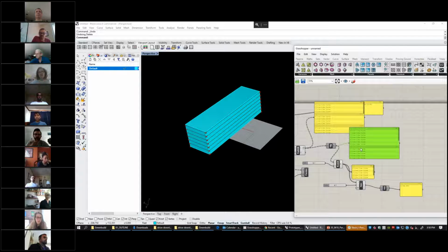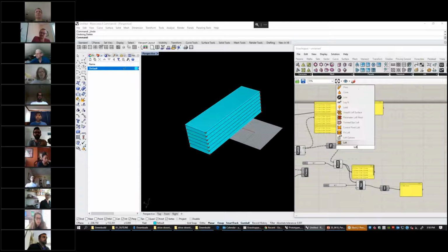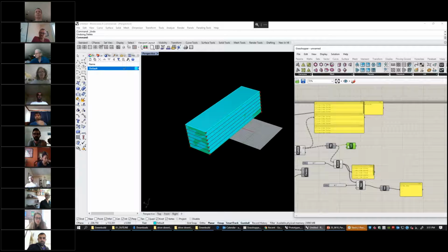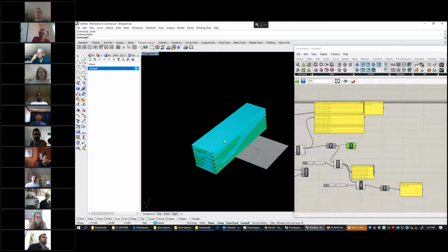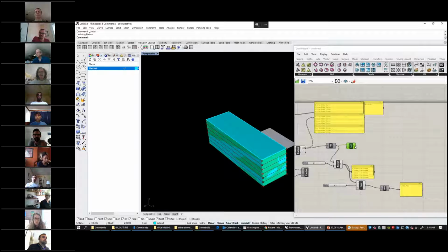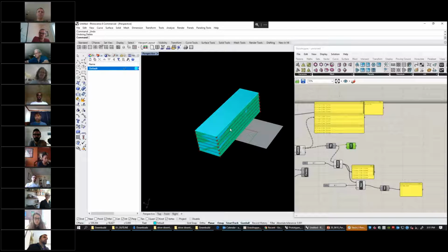And so then we can loft. Use the loft command to loft along those sets of curves. So it's basically going to look at your trees and say, okay, I'm going to go to the list, loft along those, and then go to the next branch and loft along those, and do that for all 4 faces. So now what we have are 4 branches with 1 surface in each, and that's the lofted surface across all those contours, right? So, you know, let's do the same drill. Let's plug this guy into that, and now you see 1, 2, 3, 4, right?